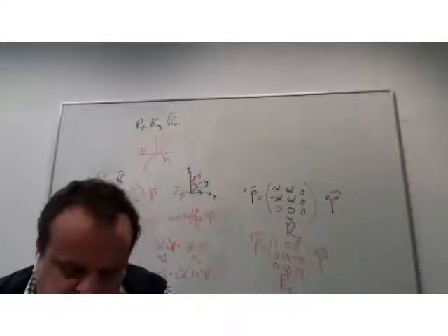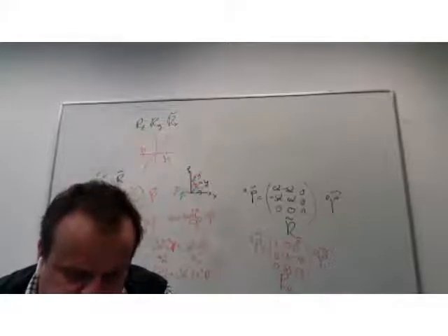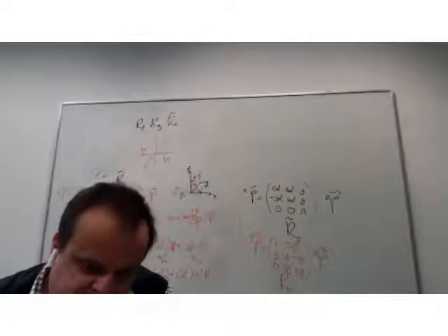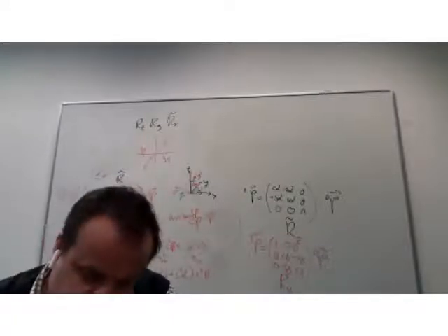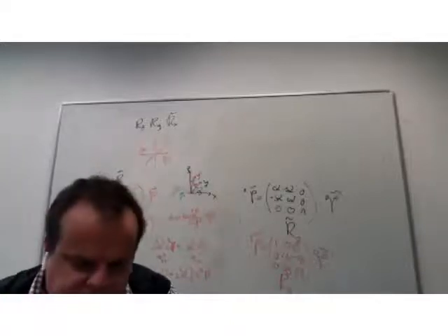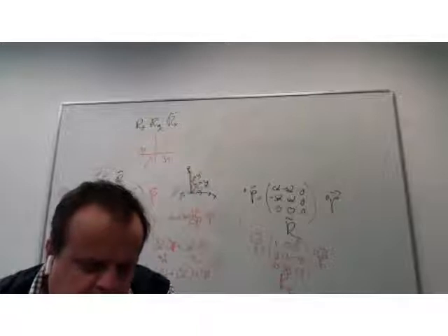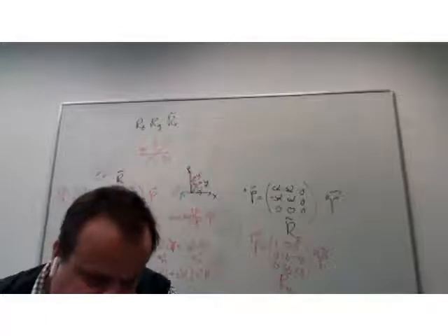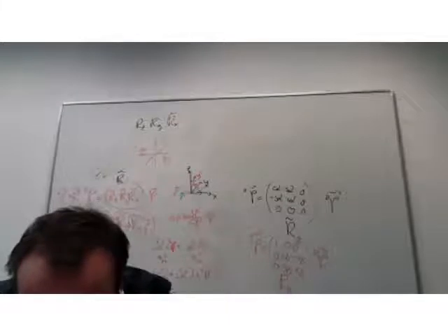It's called Gimbal lock, or singularity of this Euler representation. So if beta equals 90 or beta equals minus 90, the division here is by 0, and division by 0 is not allowed. That's why for these special cases, for the singularities of the representation, we need to predefine what alpha is. In this case, alpha is assumed 0. And the gamma can now be derived from a simpler version of it.